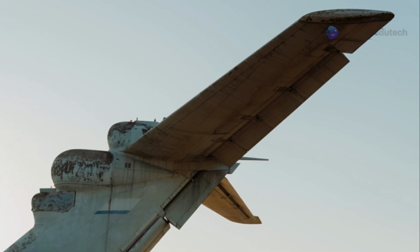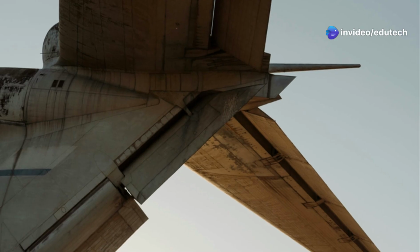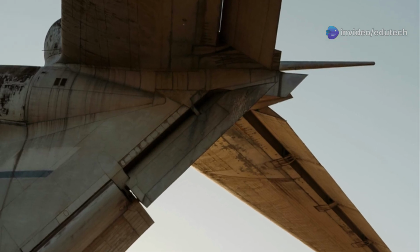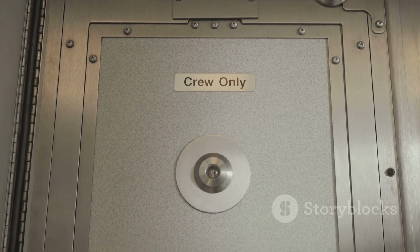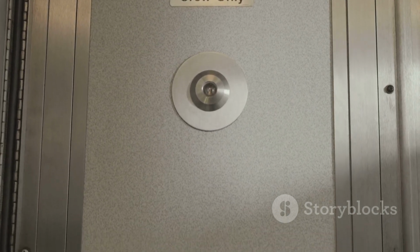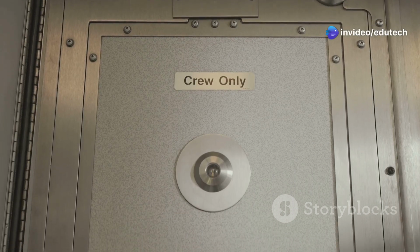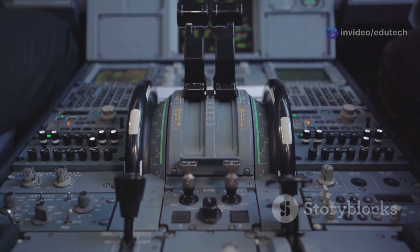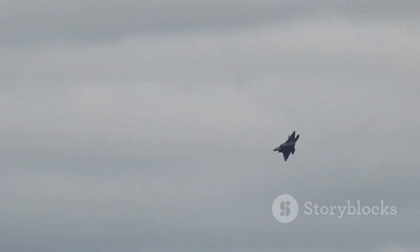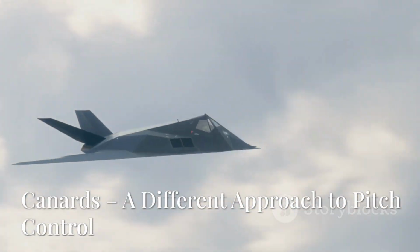The main reason for a stabilator, or really any horizontal stabilizer variable incidence device, is to minimize drag when trimming the aircraft in flight. You see, deflection of the elevator by using a trim tab causes drag and requires a relatively large elevator on big aircraft to achieve all the desired trim settings. But by varying the angle of the horizontal stabilizer to adjust pitch, less drag is created, and the elevator size and deflection can be reduced.